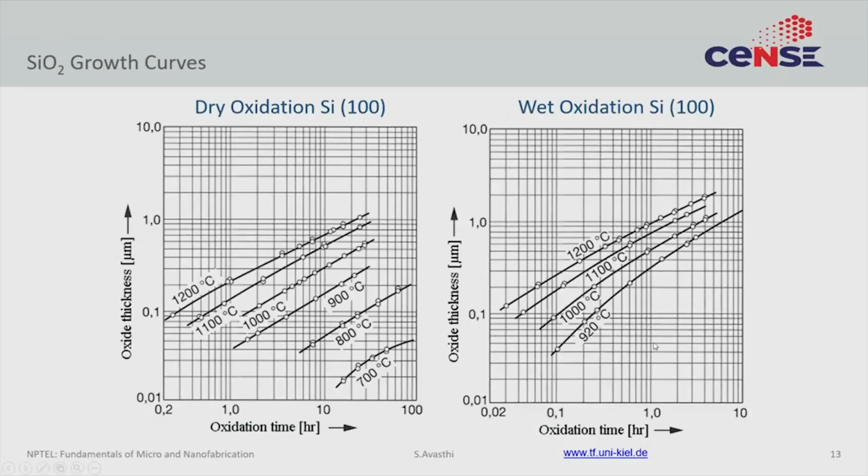In the previous few lectures, we went into quite some detail into the exact mechanism of how silicon dioxide is grown on silicon wafers by just providing an oxidant, either dry oxygen or wet oxidation. In both cases, because of the detailed differences in diffusion, solid solubility, etc., the growth rate is very different. Wet oxidation is much faster, dry oxidation is much slower. In general, the quality of the dry oxidation is much better, the quality of wet oxidation is a little worse.